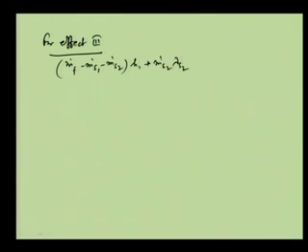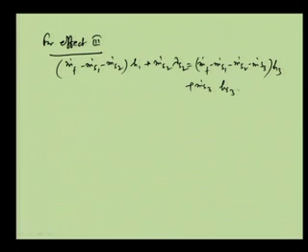So, it is another latent heat. The latent heat of evaporation will change because the temperatures are different for the steams. The latent heat of evaporation or condensation is different, and that will be equal to m dot f minus m dot s 1 minus m dot s 2 minus m dot s 3 into h 3, plus m dot s 3 into h s 3. So, this is what is being done.